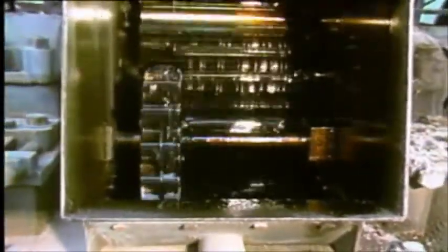Many substances that are added to lubricants are liquids rather than solids. Some of these additives reduce friction under conditions of extreme pressure, such as between gear teeth. As gears mesh together, the teeth rub against each other under great pressure. This severe rubbing can actually wipe away the protective lubricant and expose the bare metal.